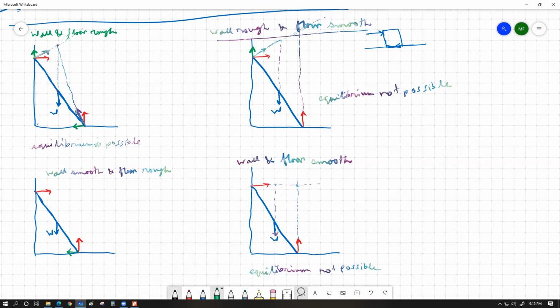So now if we try to find out the possible cross point of all the forces, let's say I extend this one a bit to the horizontal, I extend this one a bit to the upward direction, but I can find out that it is possible that the resultant force of this point might actually work through this point. I'm not saying it will happen, I'm saying it is possible. Okay. So in this case also we can have equilibrium possible.